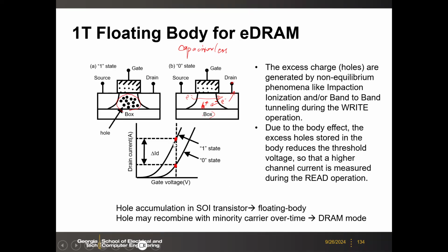And the benefit is that we do not have the capacitor, so that will ease the integration with the logic. The big challenge for conventional DRAM to integrate with the logic is the capacitor. Either you have a deep trench or a standing cylinder cap, stacked cap, and that's not very friendly for the logic.